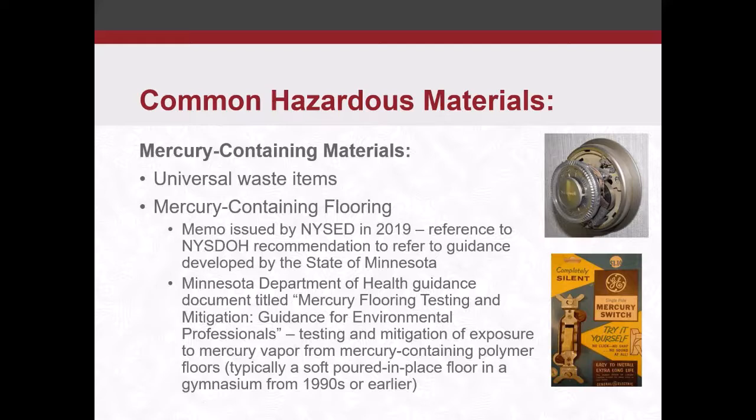New York State doesn't have any regulations or requirements for it, so they refer to Minnesota Department of Health guidance. The Minnesota Department of Health has a document titled Mercury Flooring Testing and Mitigation, guidance for environmental professionals. So that's very useful to refer to when you are designing mercury floor removal. But the actual procedures and methods are left up to the designer. So you're going to want to reach into those industry standard protocols, what methods have been successful in the past, and go off from those and continue to try to improve upon them.